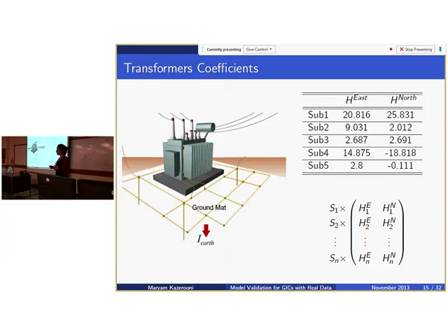The information which we got was quite accurate, except for the substation grounding resistances. Substation grounding resistance is the resistance of the ground underneath the substation, and that depends a lot on the soil condition. So it's hard to measure accurately, and we don't usually have it available very accurately. We got some data, but we knew that it's not very accurate.